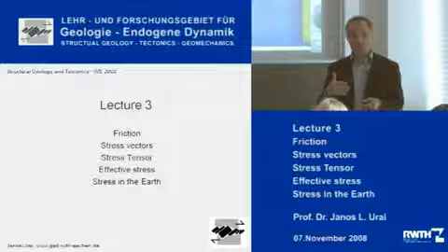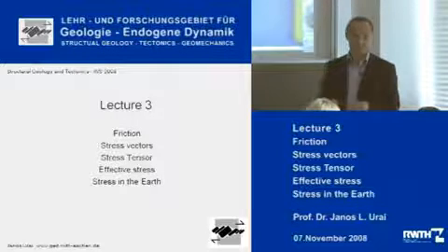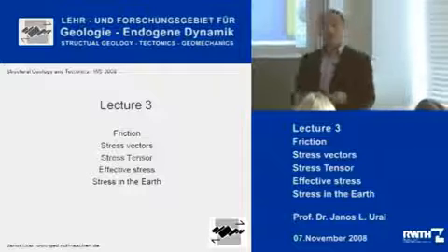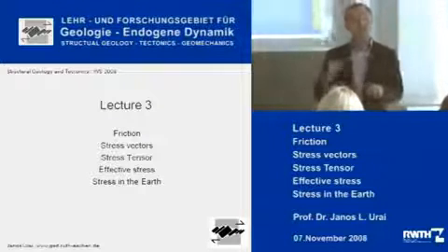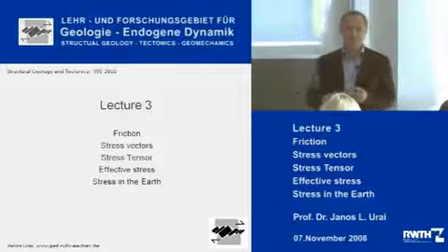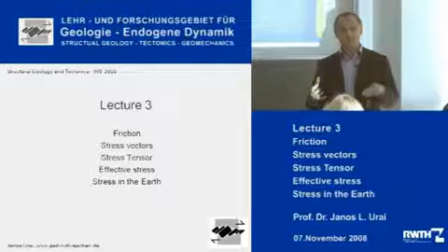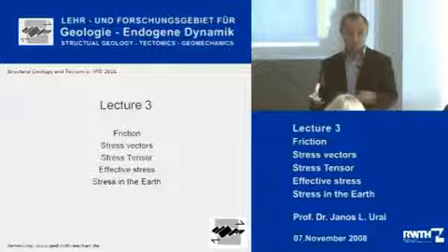You have to really consider what scale you need to describe deformation as homogeneous. The D-tensor is a very simple linear transformation that transforms a circle into an ellipse, and it really just describes the change in shape, the deformation.